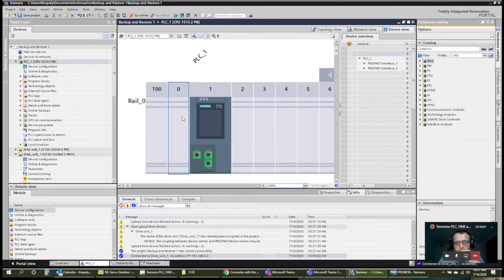Right. Okay, so that brings to mind, I'm getting a little specific about a job that we're quoting, but basically, if I'm going to have a Profinet system, then if I use a non-Siemens drive, that drive also has to support Profinet, if I'm understanding you correctly.